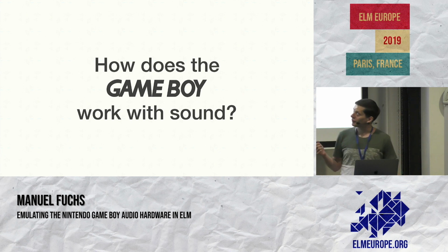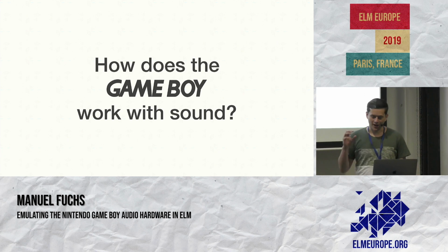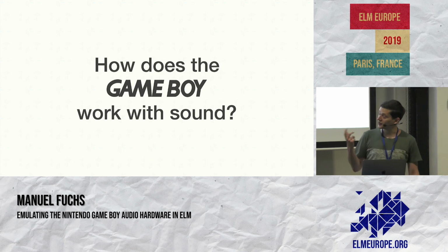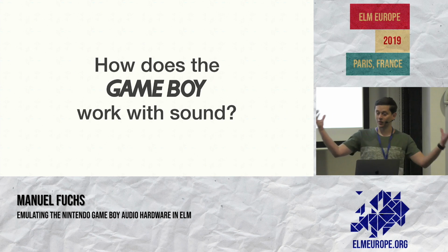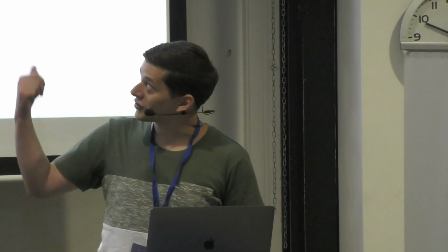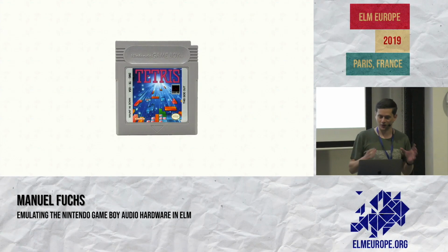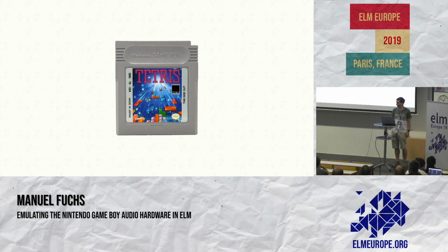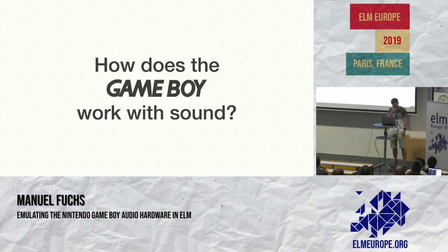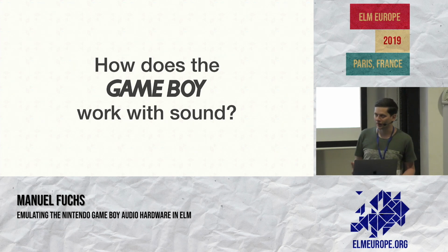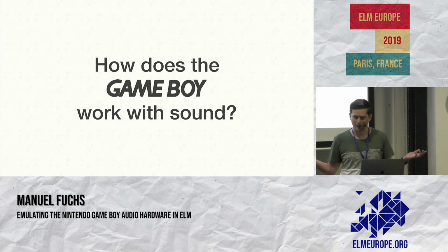We have 8 kilobytes of RAM, a 1 megahertz CPU, and games had to fit on tiny ROM chips, often only kilobytes in size. And in this context, audio files require huge amounts of storage. Take the Tetris cartridge, for example. If we would fill the Tetris cartridge with the Tetris theme as audio, this is all we could store. That's 400 milliseconds. So compressing the audio data is also out of the question. We only have 1 megahertz to work with, and we actually want to have some gameplay, right?